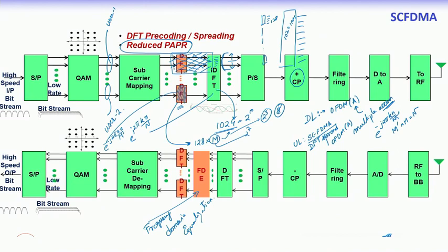So, this would make the things appear like single carrier. So, what we have, one single carrier wideband, another single carrier, another single carrier. So, it is still multi carrier, but each one of them are having a wider subcarrier bandwidth, only because it helps reduce PAPR. Now, at the user equipment side, so when we are doing uplink, user equipment is sending information to the base station. So, if one does DFT spread, PAPR is less. If PAPR is less, then one can go for the higher transmit power, one can go closer towards saturation. The efficiency of the power amplifier is higher, as well as one can radiate higher amount of power, and hence the overall system improves the power budget of the system, and coverage can be improved.